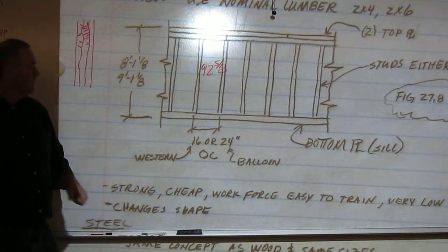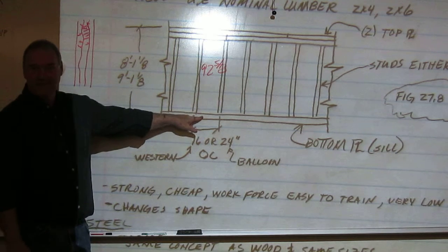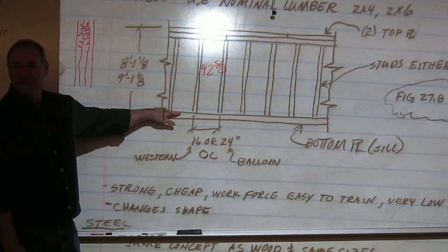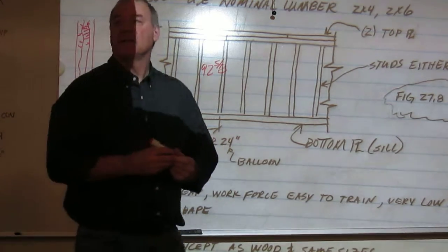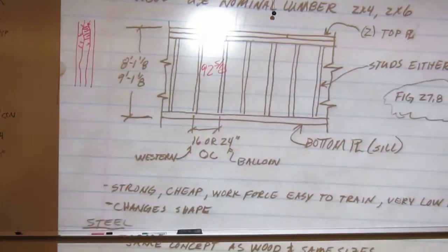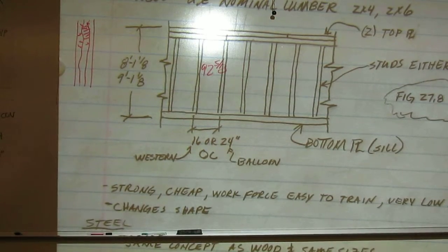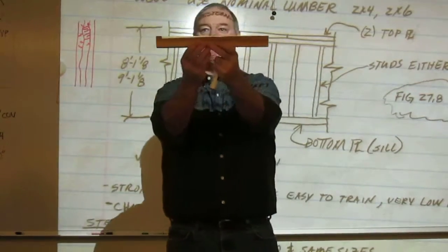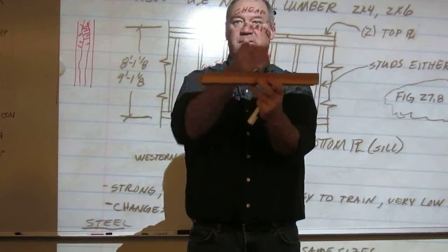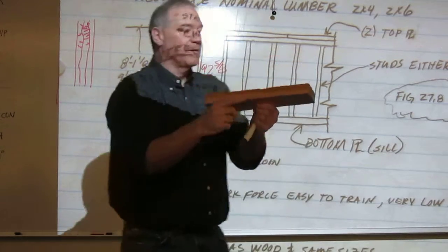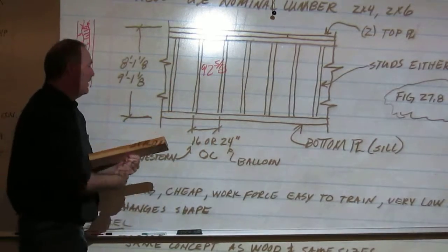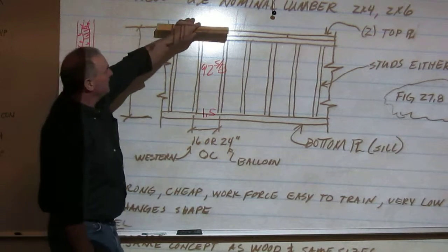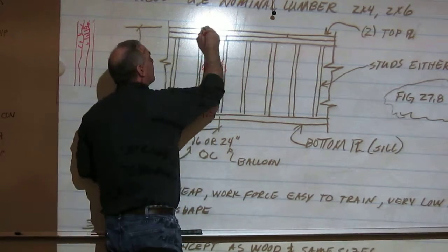Well, let's add up the height. I've got a horizontal stud sitting here, or a bottom plate. This is the 1.5 inches, by the way. Juan, do you got those pieces of wood on you? They're right up here. Okay, so the bottom plate and top plates, they're not sitting like this. They're sitting flat, in this configuration. So what's this dimension right here? Okay, so that's 1.5 right here. I have 2 of these in the top plate configuration right here. That's 3 inches.